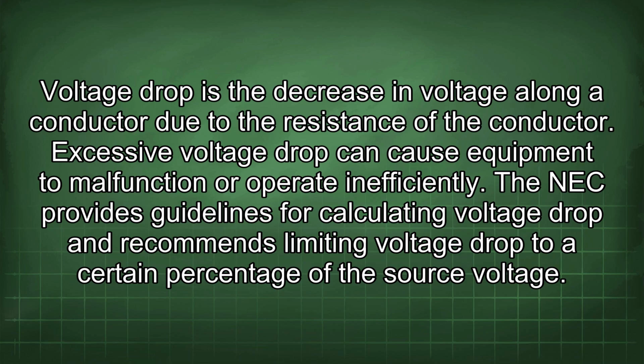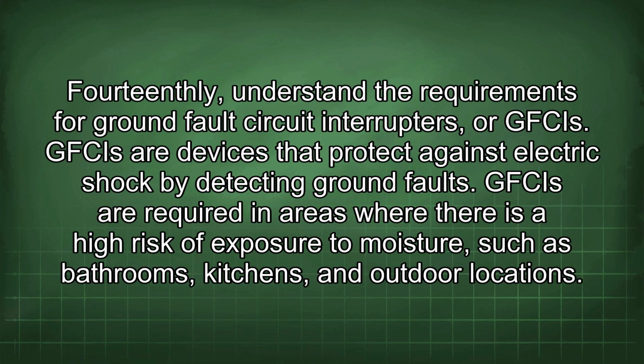The NEC provides guidelines for calculating voltage drop and recommends limiting voltage drop to a certain percentage of the source voltage. 14thly, understand the requirements for ground fault circuit interrupters, or GFCIs. GFCIs are devices that protect against electric shock by detecting ground faults. GFCIs are required in areas where there is a high risk of exposure to moisture, such as bathrooms, kitchens, and